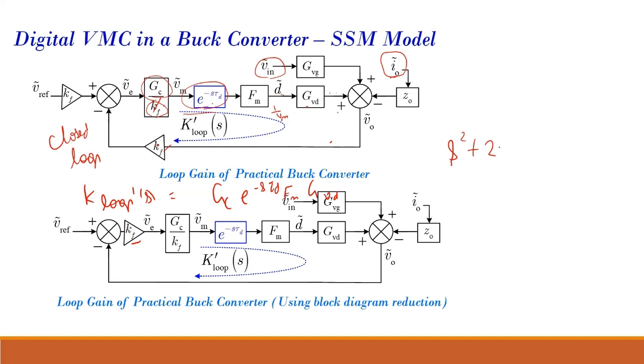No, see, for a second order system, something will be here, this is your denominator. So your 2 zeta is equal to 1 upon Q. So the quality factor is 1 upon 2 zeta. Based on the transfer function, you can get your quality factor.